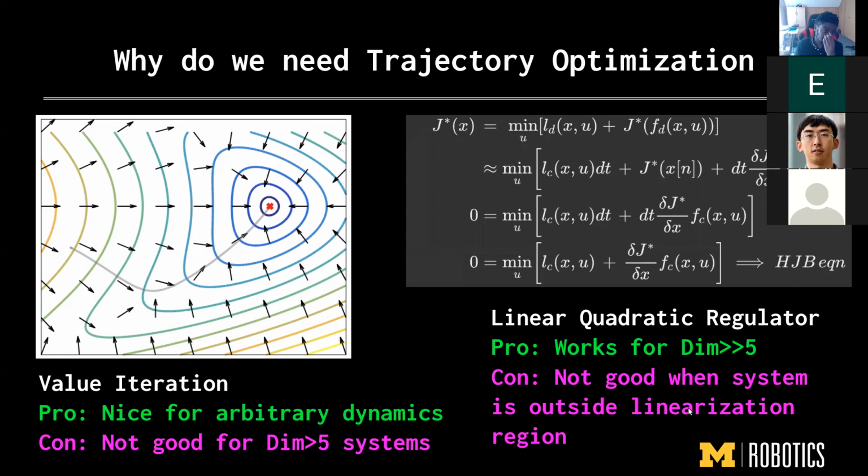So for dynamical systems like, say, the Atlas, which is definitely nonlinear, what you usually have to do is linearize it using a first order Taylor expansion. That's in the second line of this equation. Basically you linearize your dynamics at a specific point, or the region where you want to act.